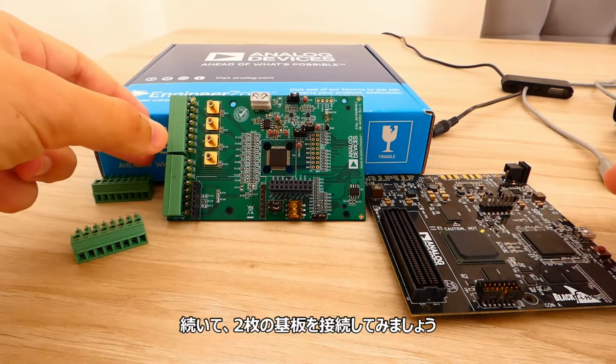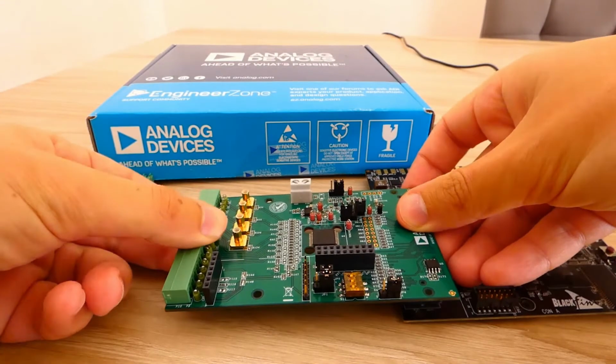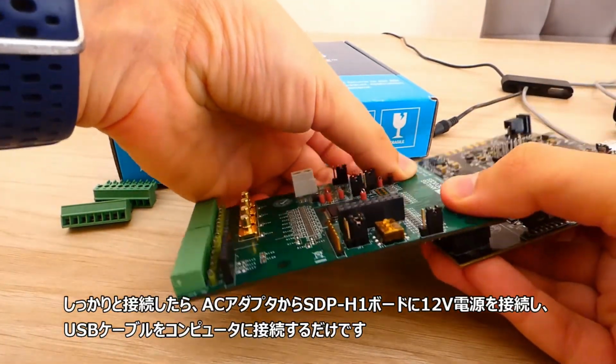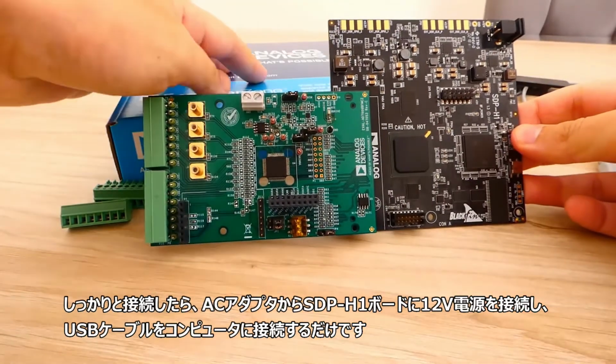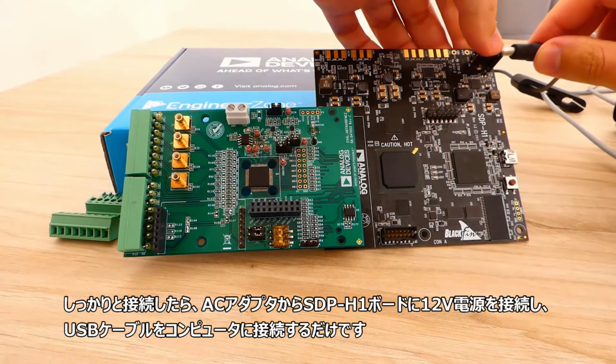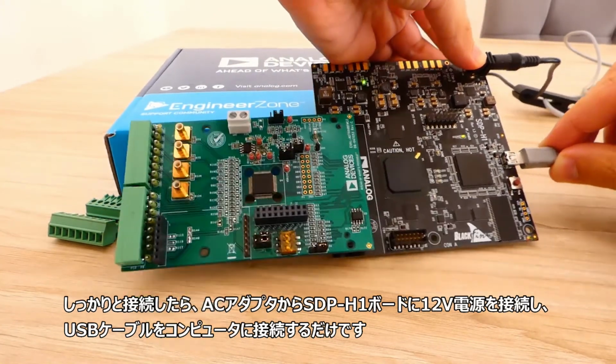Now that the hardware is explained, let's plug the 2 boards together. Once these 2 are plugged in firmly, we just need to connect the 12 volt supply from the wall adapter to the SDPH1 board, and then connect the USB cable to the computer.